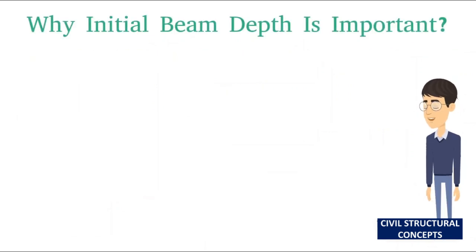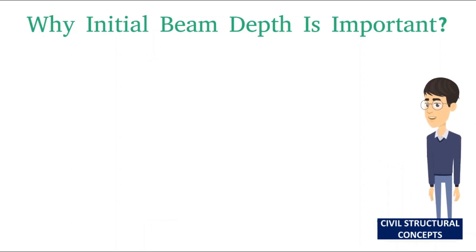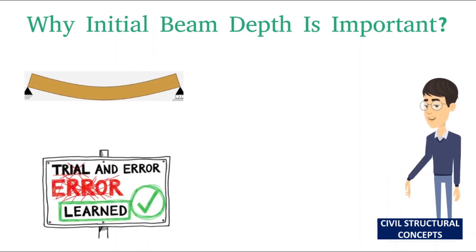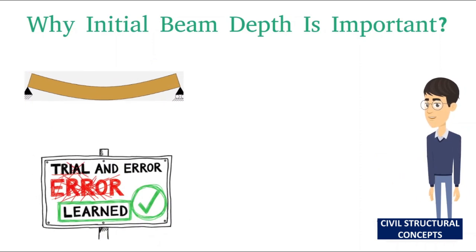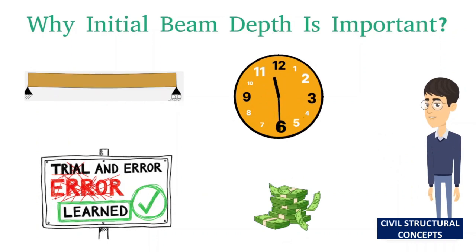Let us begin. Before starting the detailed design of a beam, engineers must assume an initial depth. This initial depth helps in controlling deflection, reducing repeated trial and error during design, saving time, and ensuring that the beam remains safe and economical.